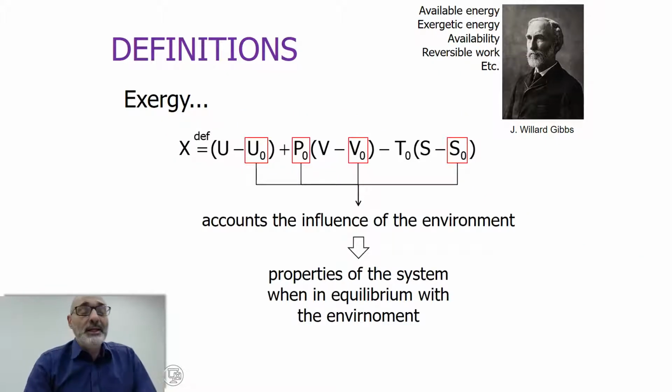So, let's analyze this definition. As I was saying, U0, P0, V0, and S0 account for the influence of the environment, okay? Very, very, very important observation. U0, P0, V0, and S0 are not thermodynamic properties of the environment, okay? They are thermodynamic properties of the, let's say, orange substance when it's in equilibrium with the environment, okay?